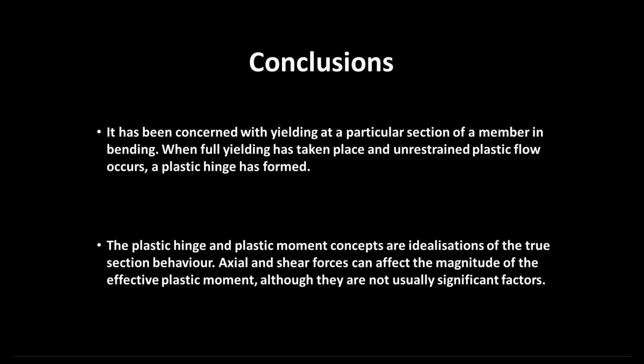From the conclusions, what did we learn? It has been concerned with yielding at a particular section of a member in bending. When full yielding has taken place and unrestrained plastic flow occurs, a plastic hinge has formed. The plastic hinge and plastic moment concepts are idealizations of the true section behavior. Axial and shear forces can affect the magnitude of the effective plastic moment, although they are not usually significant factors.